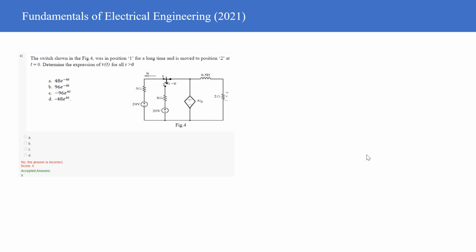So we have understood the working operation of an inductor. Now we can also write the initial current. From the conclusions which we have drawn in the previous segment, for time t less than 0, since it is closed for a long time, the inductor will behave as a short circuit, right? And the current which will be flowing in the inductor will be given by